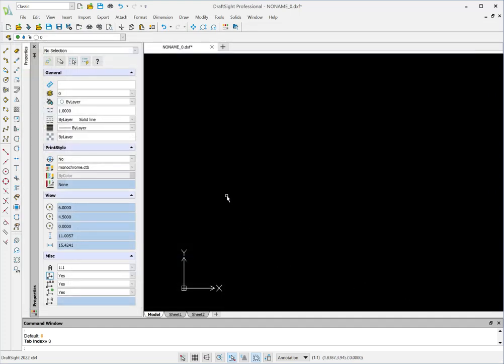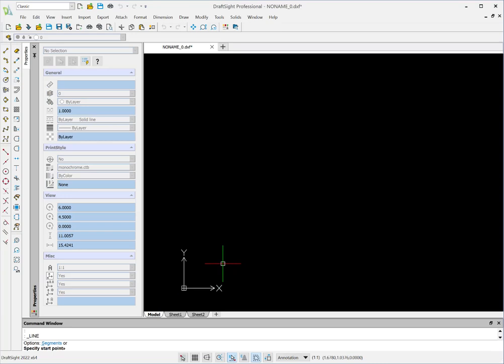All right, that's a quick overview of the arrangement and how I set up Draftsight. Now let's go into drawing a simple line. So if I want to draw a line, I click over on the line button on the left in the draw toolbar and I click it, and now down in the bottom it's acknowledging that we're drawing a line and it says here's your options. Well, we're not going to use this option, so we don't do anything, and it says specify the start point,